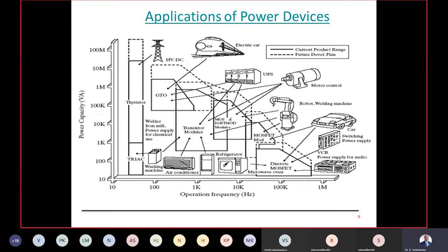So when you handle less power, like if you are charging your cell phone, the adapters handle very high switching frequency. When they switch at very high frequency, the size of the magnetics, the coil, the transformer, and even the capacitor size will go down drastically. I get compactness.